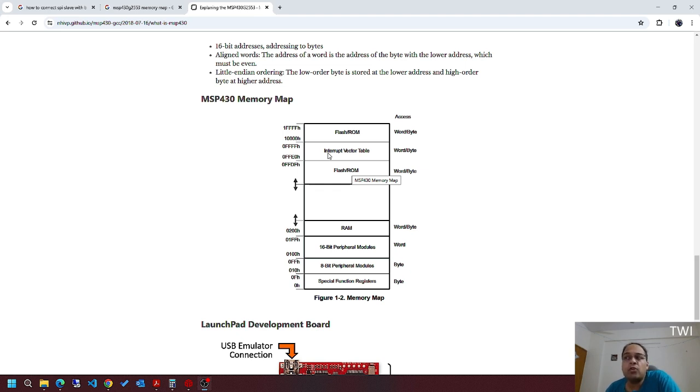I am not going to do all those things over here, because that is out of the scope of this video. It's a separate task altogether. But what I can say is that it's best not to touch the C000 configuration that's there. We rather take a separate location, which I have taken here as D000, which is again within the flash ROM area.